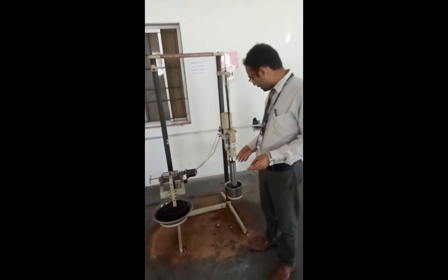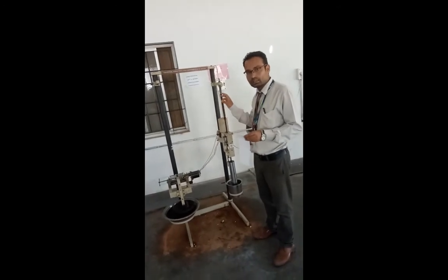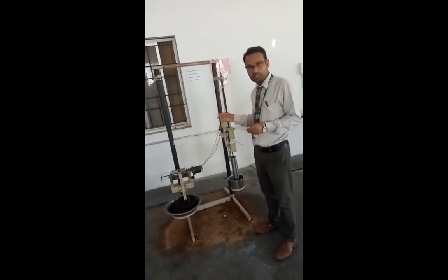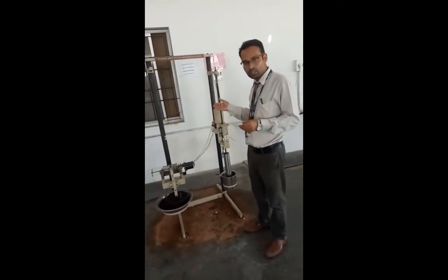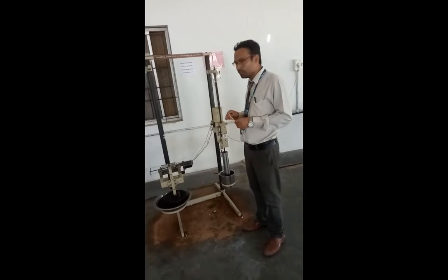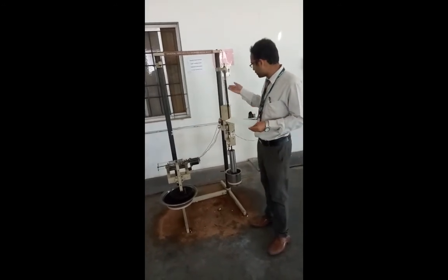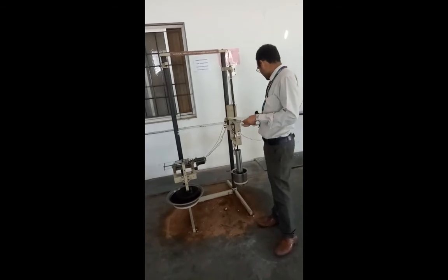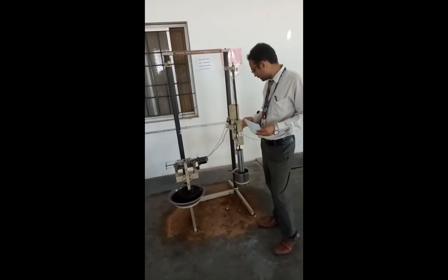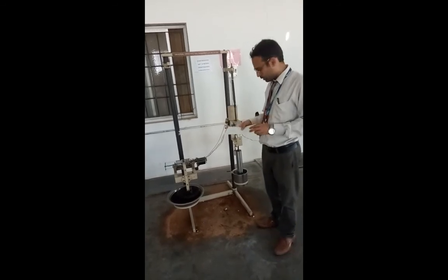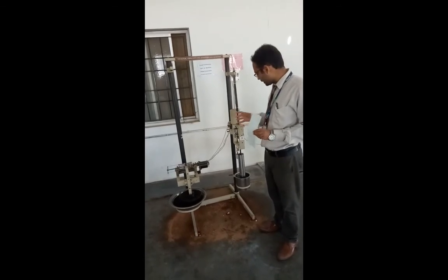Now I am going to the aim of the experiment. The name of the experiment is damped longitudinal vibration. The aim of the experiment is to determine the angular frequency, time period, and logarithmic decrement of the damped longitudinal vibration. The apparatus required is the motor, the spring, the damper, this drum, and mainly a sketch pen and this graph sheet. These are the apparatus required to conduct this experiment.